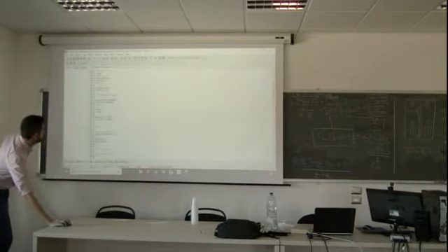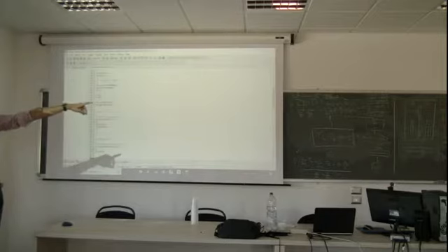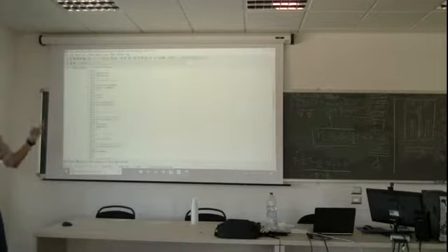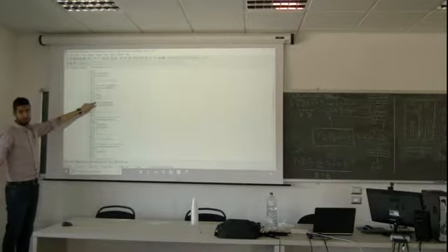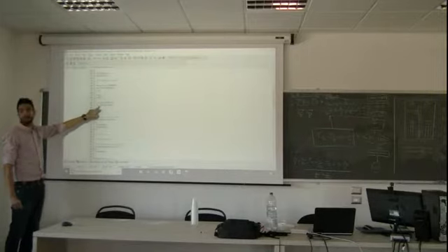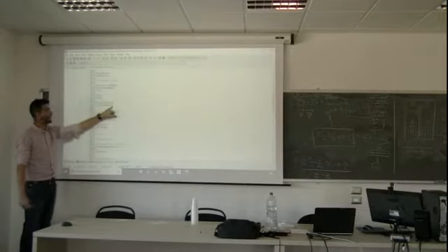Now, after I input parameters, let's say calculation of coefficients. Which coefficient do I have to calculate? Here, just 2. Those 2. Right? Because it's Cartesian coordinates, there are no areas, there are no different volumes. I just need to compute delta x1 and delta x2. And by definition, delta x1 is thickness 1 divided by n, thickness 2 divided by n.